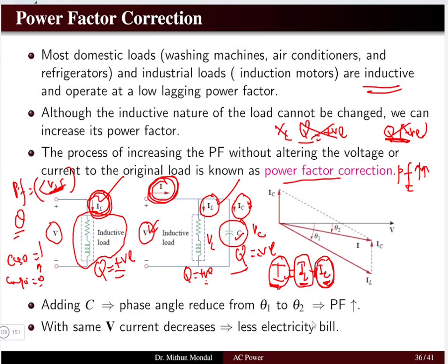Okay, now if I draw the phasor diagram, on the x-axis, the reference axis, we have voltage. It means V RMS angle 0 degree. So this is the reference voltage. Now we have an inductor and a capacitor. You know that capacitor current is leading the voltage by an angle of 90 degree. Now the inductive current, which is due to the inductive load, has two components.